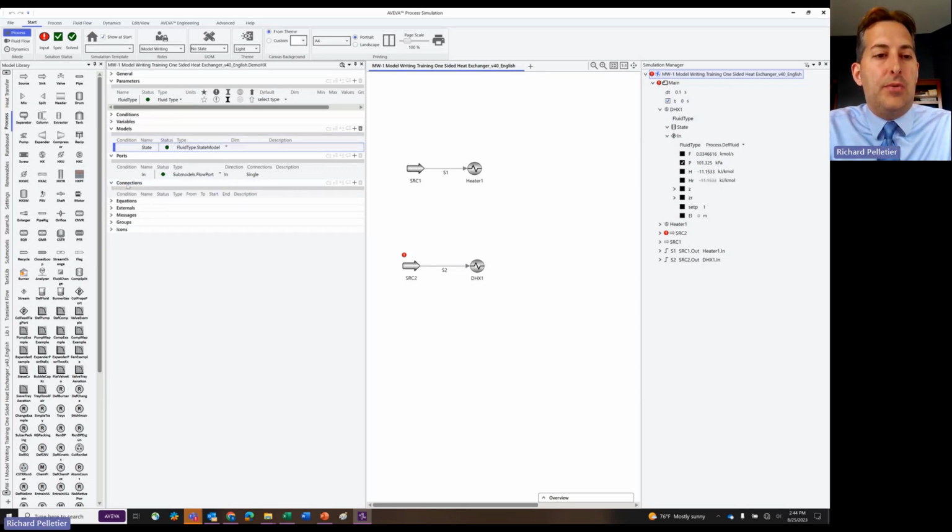All right, so now we have the state submodel set up. Now we want to start defining some connections. Connections are one-to-one relationships within the model, right? So we commonly use these wherever we have equations where this value equals this value, this variable equals this variable. That's a one-to-one relationship, but that's a variable connection. You can also have connections that are parameter connections, that are port connections.